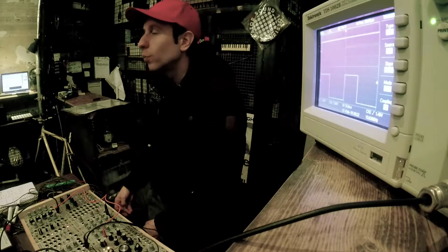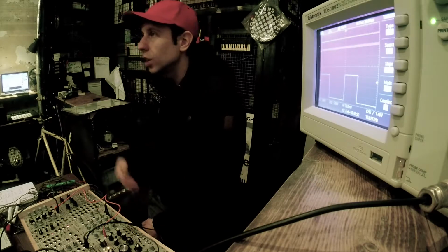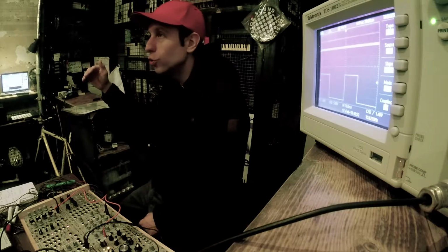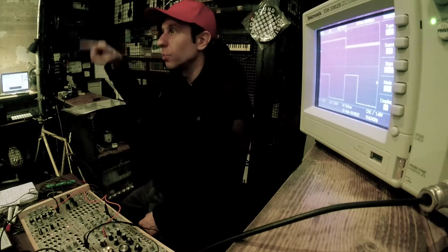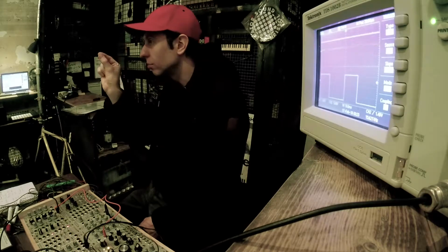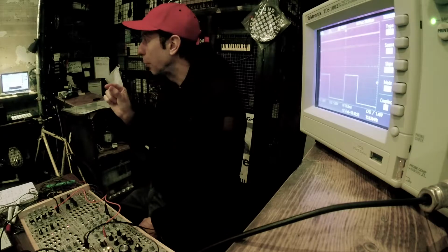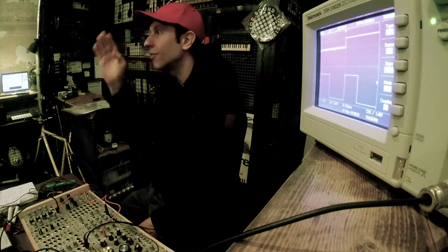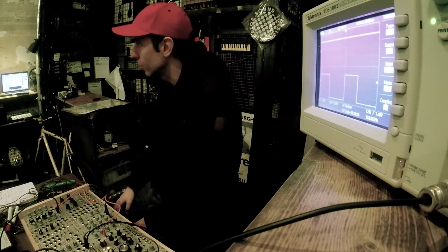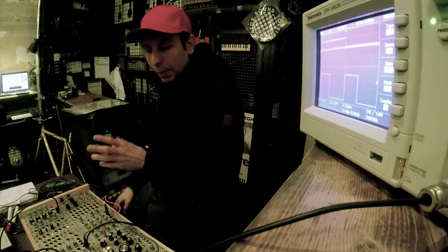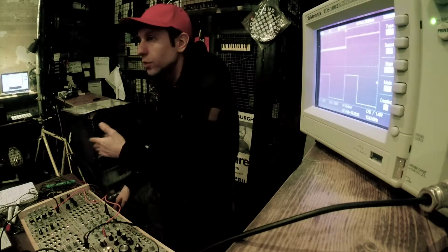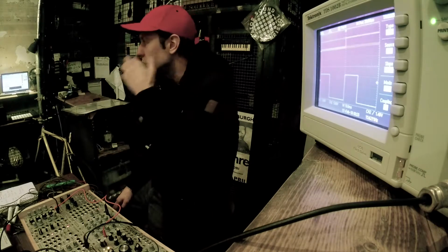Now what you have with analog white noise is a continuous flat line, but with digital noise you actually get a kind of comb pattern based on your bit depth, because you cannot choose a value in between your grid points. You have a given number of possible outcomes. It's a discrete histogram essentially. The probability distribution function is the continuous counterpart of the histogram. The histogram tells you how often something happened.